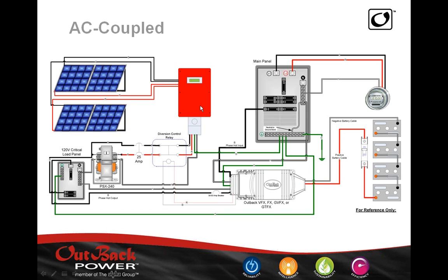And so if the grid goes out, even if the failure happens during the day, once the voltage or frequency deviates, or has an excursion away from these two windows, the inverter has to stop injecting power into the grid or into the system.